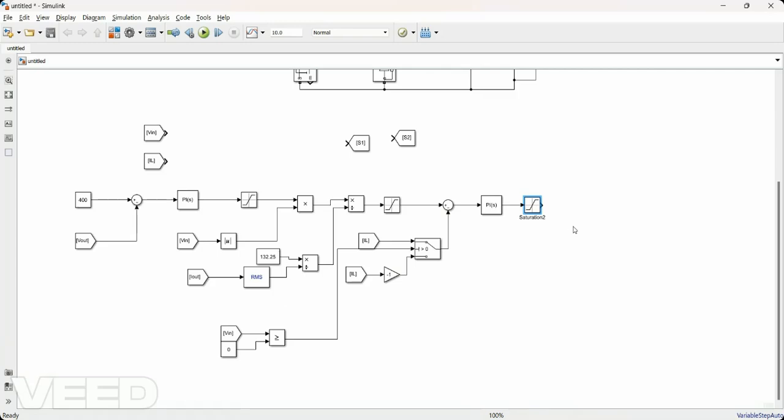Okay, so next up, when the error is greater than 0 and when the error is less than 0. In the second chapter of this course, we looked at which switch we should use when we are trying to increase the current through the inductor. Basically it's the switching which will ensure that the inductor is getting charged. So that is how we have to define it now.